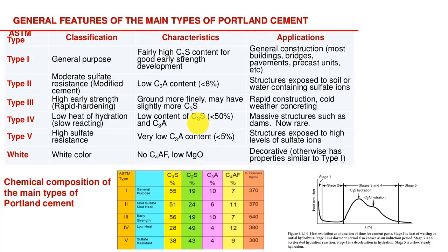A temperature around 35 to 40 degrees Celsius is a very conducive temperature to initiate the rate of hydration. If you increase the ambient temperature, it would accelerate your hydration reaction. But there is a limit at 60 degrees Celsius, where you would have the hydration reaction totally retarded.